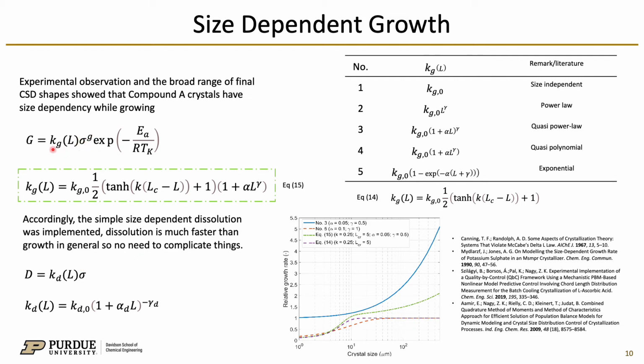Here the size dependency comes into play in these Kg and Kd terms. As another novelty of this work, we came up with our own size-dependent growth formula due to the broadening in product crystal size distribution measured by laser scattering technique and laboratory experience. Compared to the existing equations in literature, this new formulation, shown with equation 15, described the growth behavior of compound